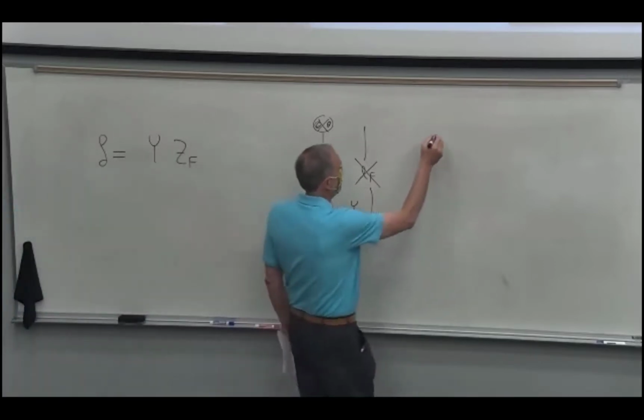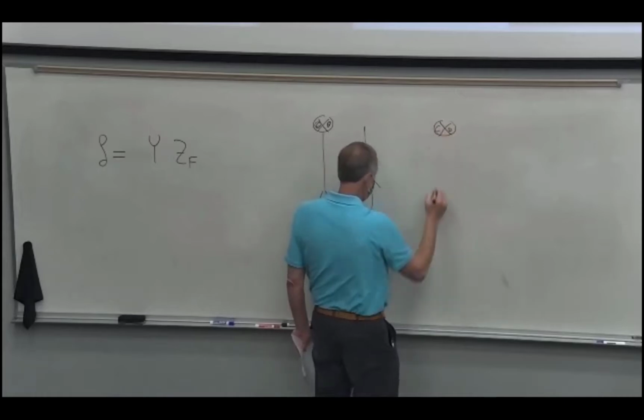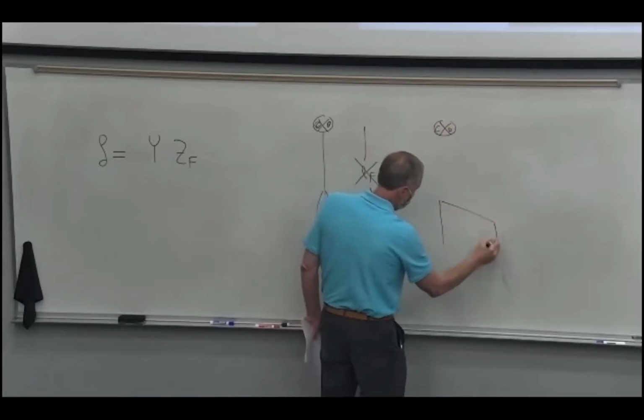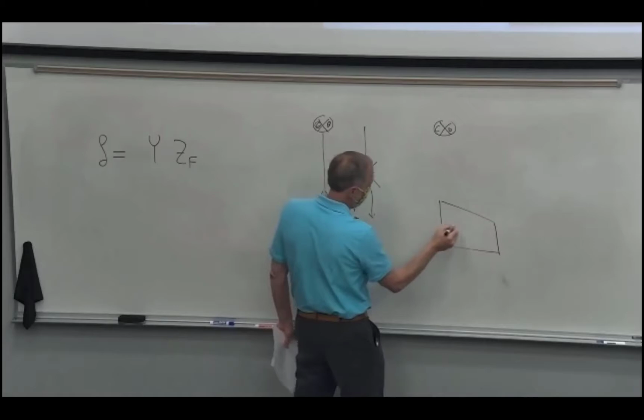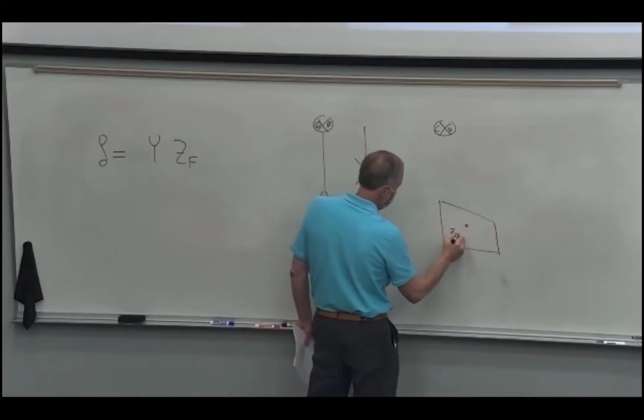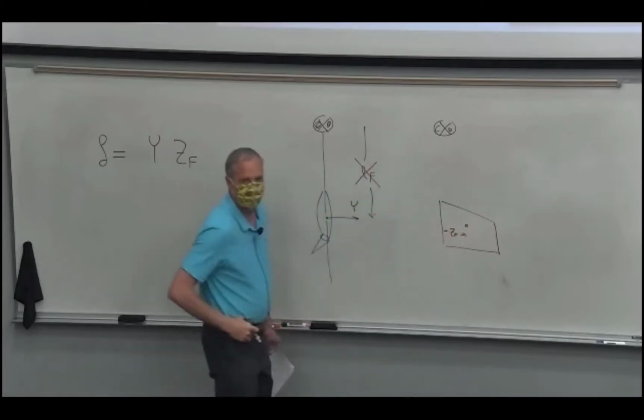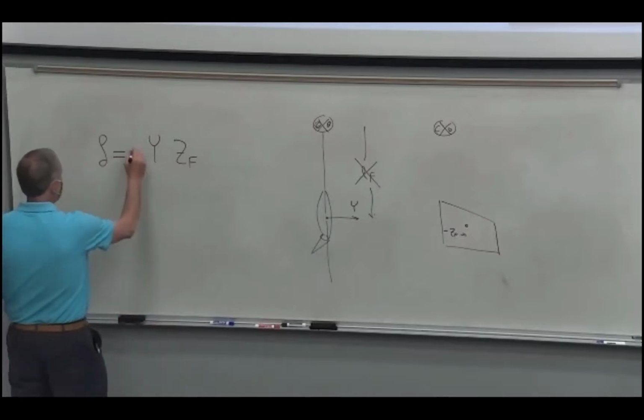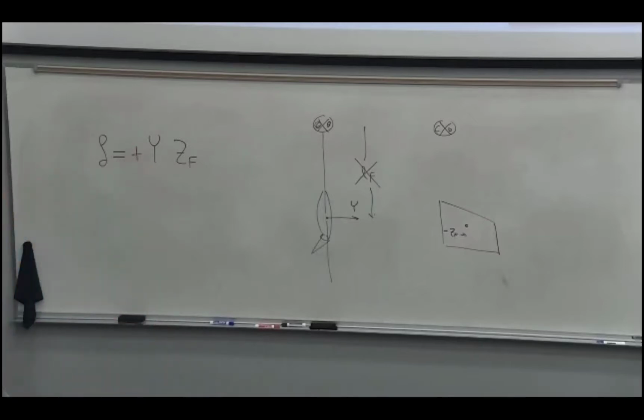So if you want to draw another picture, this would be good to draw of the fin like this. This is a side view showing that distance. Why did I put a plus sign here? The X axis is forward. Curl your hands. So a positive Y gives a positive rolling moment as long as the fin sticks above.